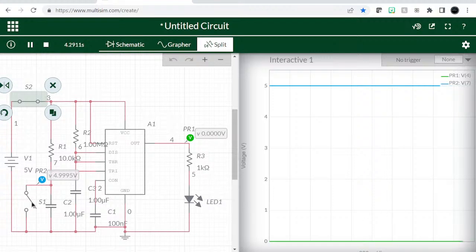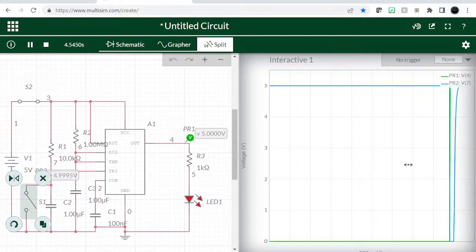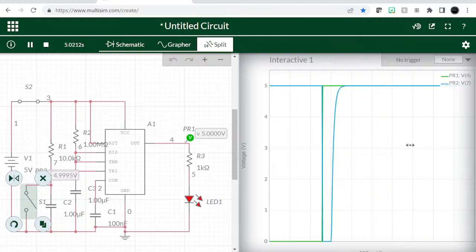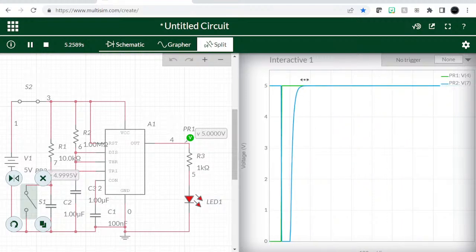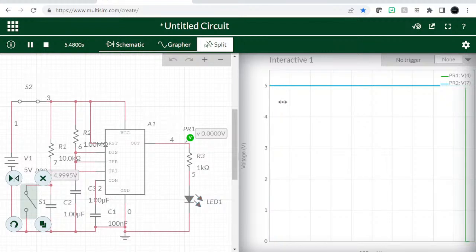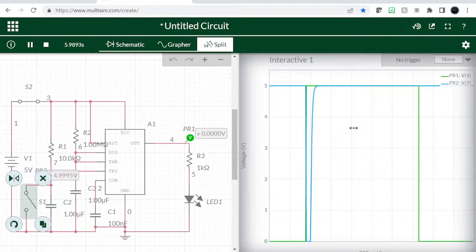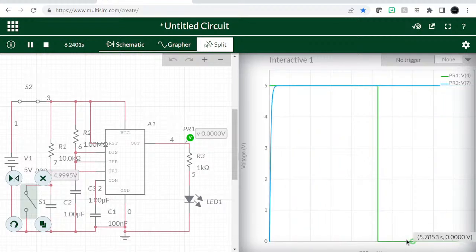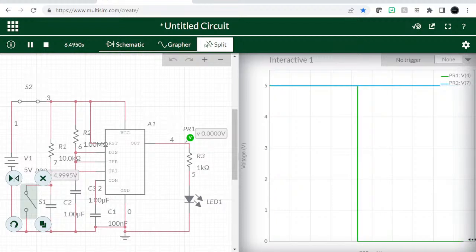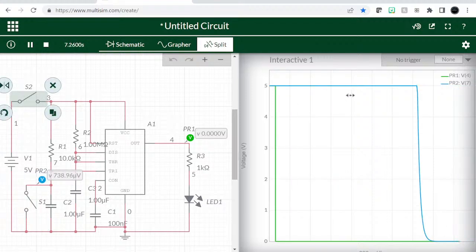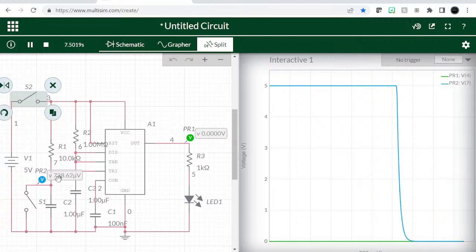So your system will be designed in such a way that this will create a reset. Now I'm going to trigger this. I'm going to click it and release it. When I clicked it, as you can see on the plot, the blue line goes low and then comes back up. It's not a perfect square wave, but it builds and comes back up, right? And stays on. My monostable period times out and goes low, and you stay low forever unless something else happens. So if I go here and turn off the switch again, everything should die, right? You can see the value of the capacitor decayed. The value across the capacitor of S1 decayed.